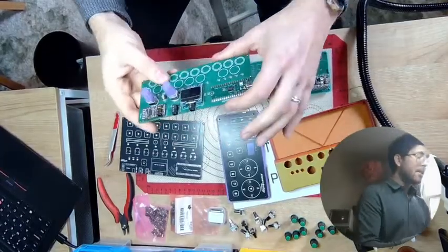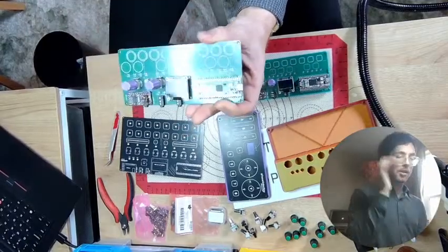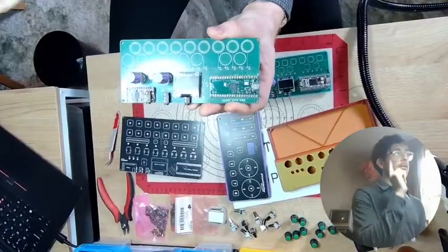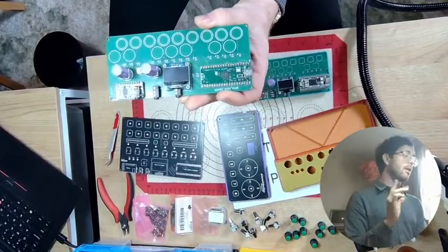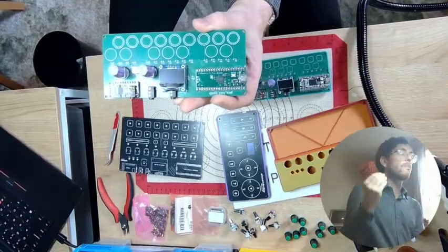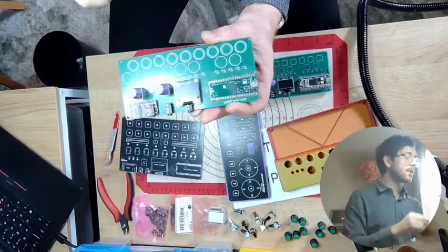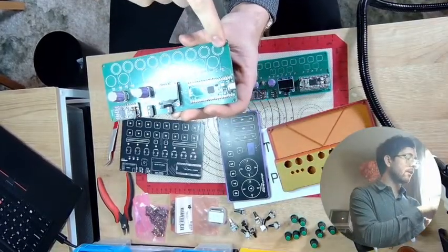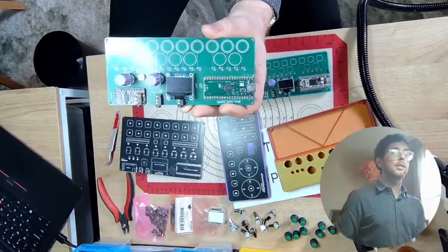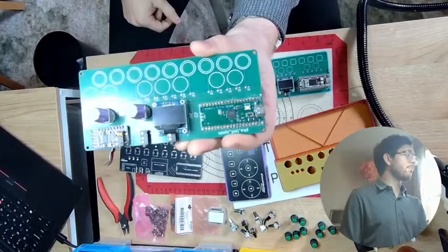Okay, cool. So this is the first one, and we have a capacitive touch here, which in CircuitPython is really easy to do because all you need is a single GPIO line. I don't know if it's restricted on other MCUs, but on the Pico, you can basically use every single GPIO pin as a touchpad if you want. And you just need a little copper pad there with a 1 megaohm resistor. I think you could probably use other resistor types, but that one's pretty easy to use.